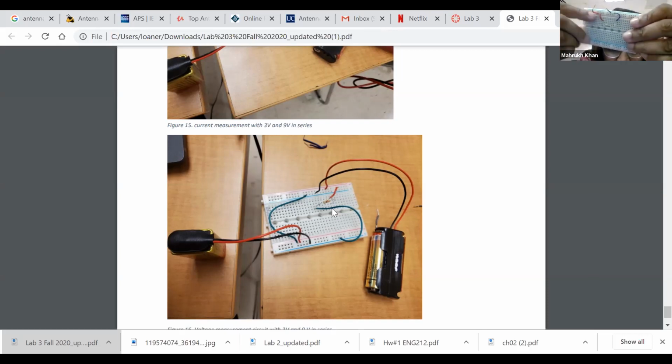Now connect your DMM leads here, where you have taken the wires out. Okay, I'm getting a reading now. So you are getting 3 point something volts? Yeah, it keeps changing, but it goes up to 3 pretty much. So it means that your battery is fine, okay? Your batteries are fine. There is something that is not connected in your circuit. Got it? Yeah, that helps. Thanks.